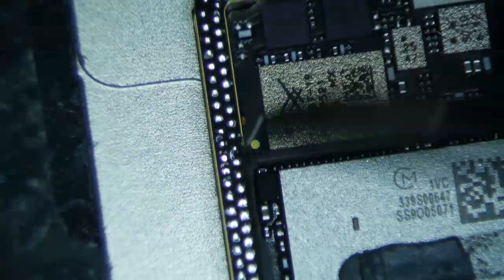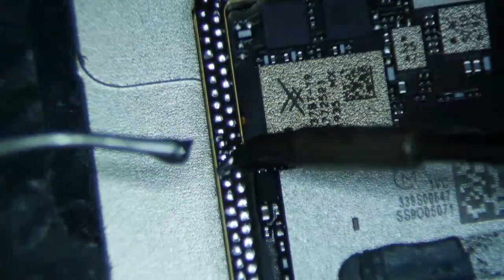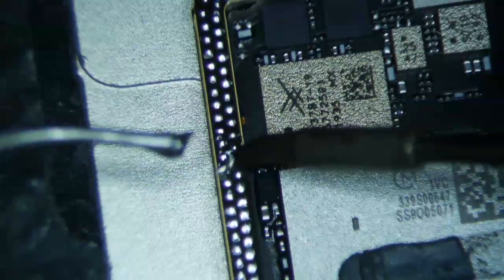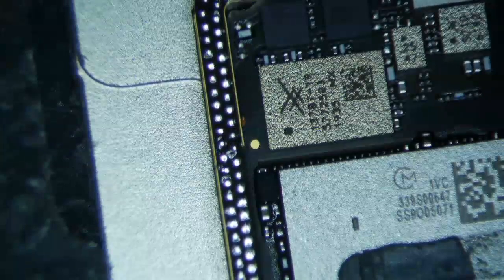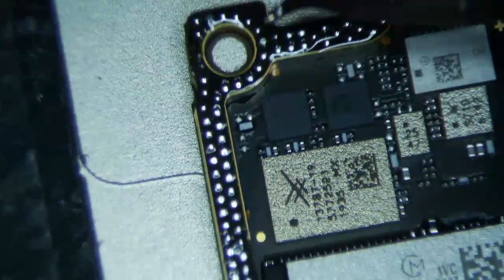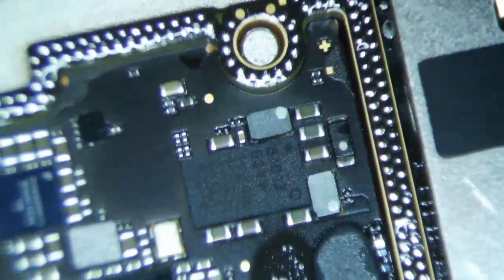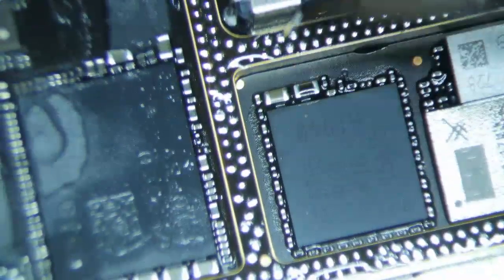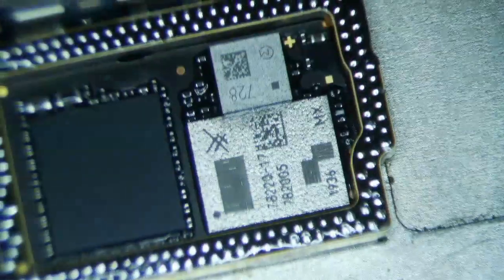You want to do this stuff before you re-sandwich it, otherwise you get your unsandwich, re-sandwich. Pain in the ass. So sometimes you have to do it anyways, but just go around here and make sure you add a little bit of solder to the joints that have no solder or have very little solder. And make sure you don't muck with the discs, okay? The discs are important. They're spacers.